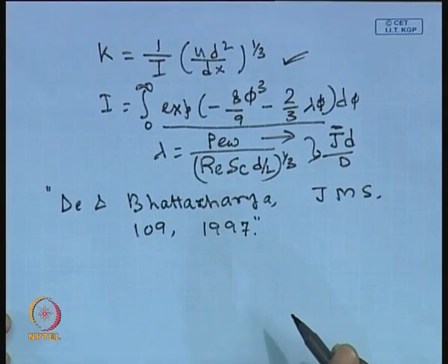Okay. So, in that case, you will be getting the profile of permeate flux as a function of x. Do a length averaging and check whether the calculated length average permeate flux is equal to the assumed value or not. If not, you have to iterate a number of times. Within 3-4 iterations, you will be getting the solution. So, that goes for the laminar flow conditions under the tubular flow module.